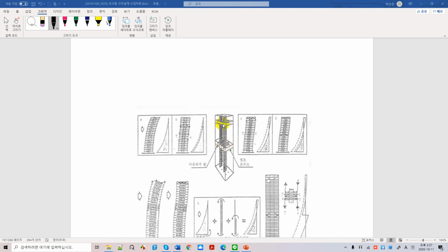Okay, and this is the belt truss. So these belt trusses are installed with the outrigger. Okay, you don't have to have a belt truss. Sometimes a belt truss does not provide the stiffness as much as you expected, but it is customary to put belt trusses with outriggers.